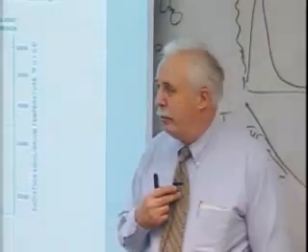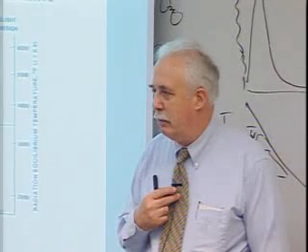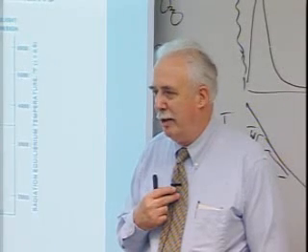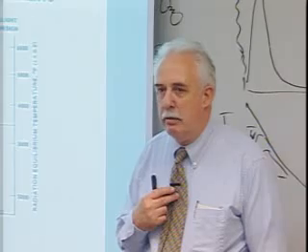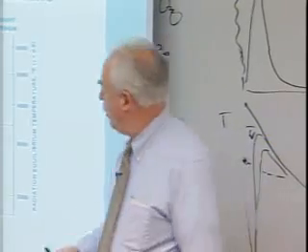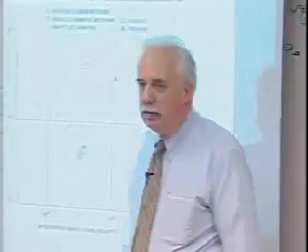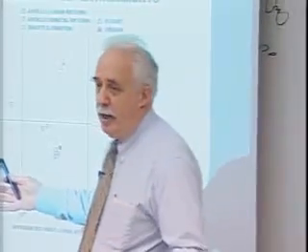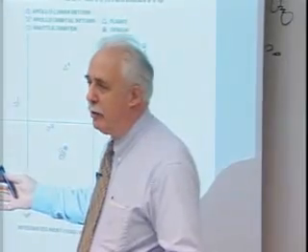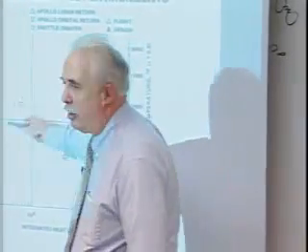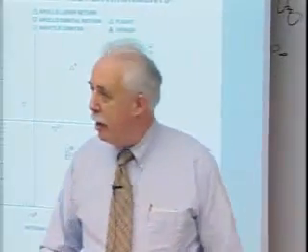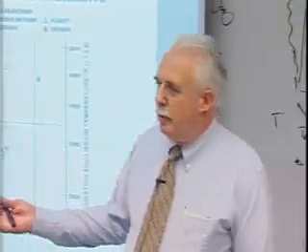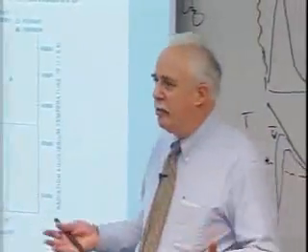Boy, I sure don't want to put too low a heating rate in. I mean, I don't want to be the cause of a failure. So I think the heating rate's going to be right here or whatever. Well, I better put, I mean, I've got to, I don't have that level of confidence. I've got some uncertainty. So I'll put 10 or 20% at least in on my heating, right? The ablator guy, he's testing in arc jets, and he does exactly the same thing.